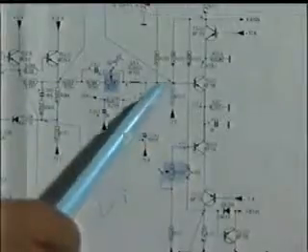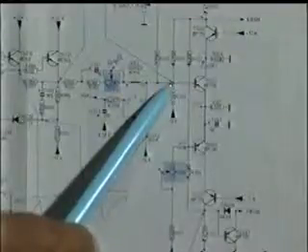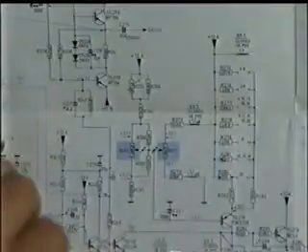Let us see in the circuit diagram. It seems the sawtooth pulse is not reaching here, either missing on the way or some problem in the sweep generator stage itself. This is the sweep generator stage, and this is the time division band switch to change the frequency of the sawtooth.